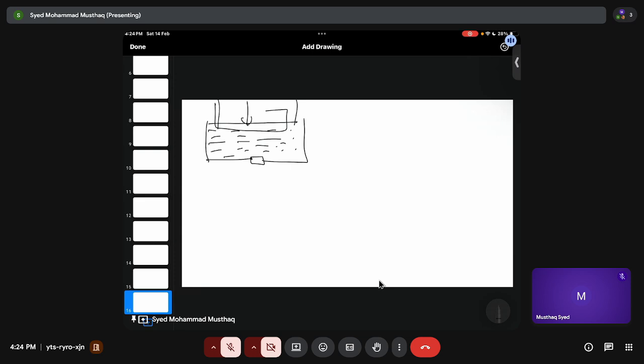Then the pressure is increased, and because the area is very small, you can use A1 V1 equals A2 V2. So A1 is very much less than A2, then V1 should be very much greater than V2. That's what happens. So when you have a very small area, the liquid will squirt out or burst out.